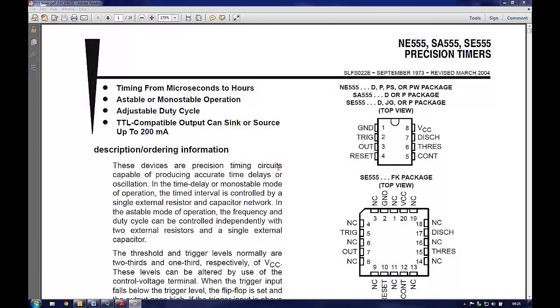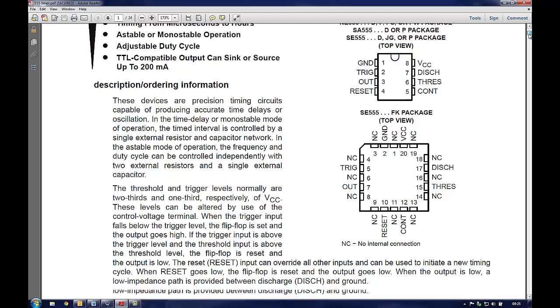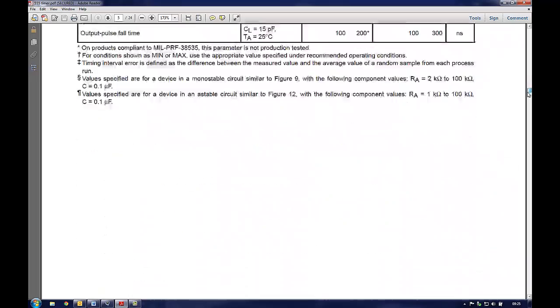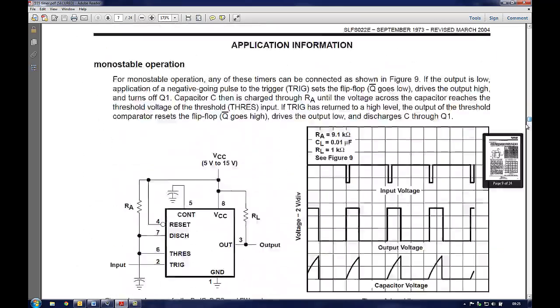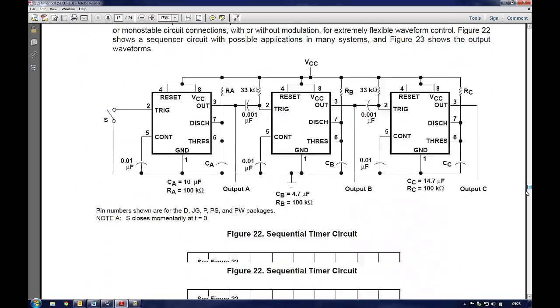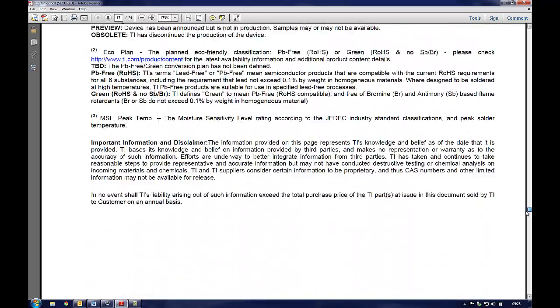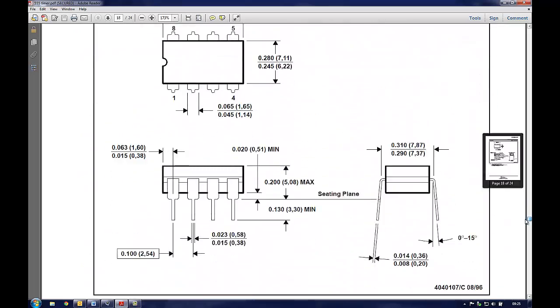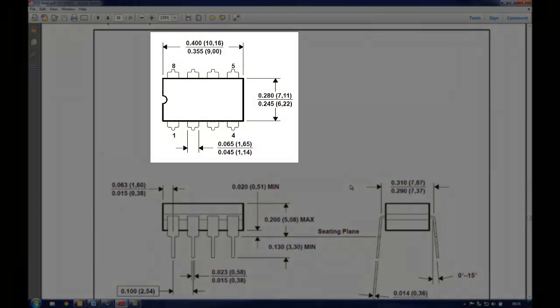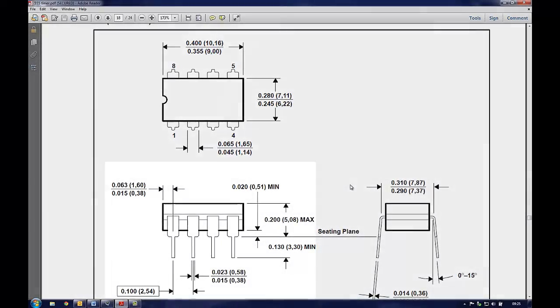To start designing custom components, it is important for the user to download an accurate datasheet and have a good understanding of what the dimensions mean and how tolerances work. The mechanical structure of the component is drawn first, and then this is linked to the schematic symbol. The user should find the section of the datasheet which discusses the physical size and shape of the component. This section will normally give all relevant dimensions of the component as well as manufacturing tolerances associated with each dimension.